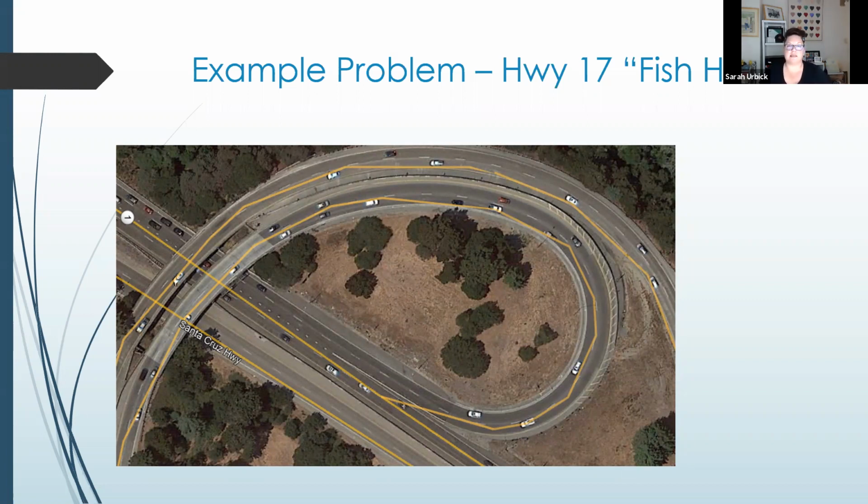So we're going to take that arc. We're going to analyze that a little bit. This is just a snapshot from Google Earth, and I had the box selected to see the roads. You see how each one of those is broken into little segments, little straight lines. There's no curves. The computer doesn't understand how to do that curve, so it draws it in segments of straight lines. It's basically what we're going to do, only we're going to say our segments are about 100 feet each.